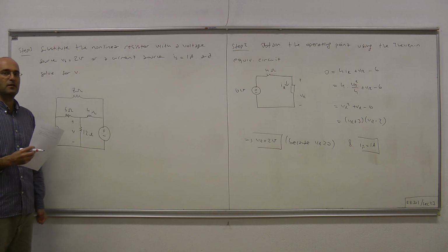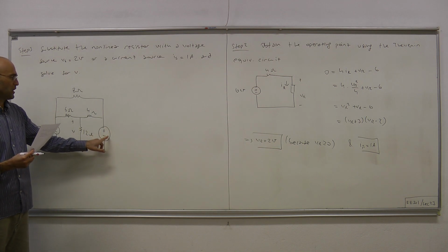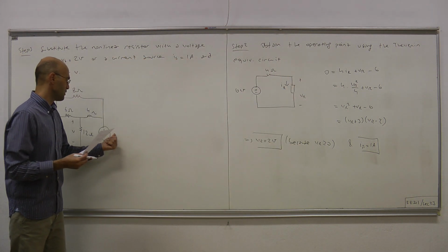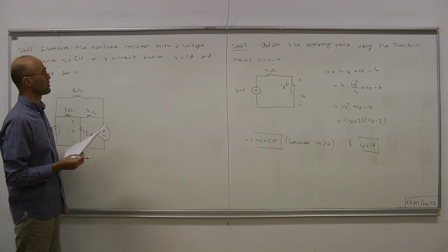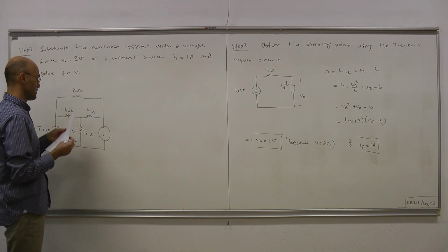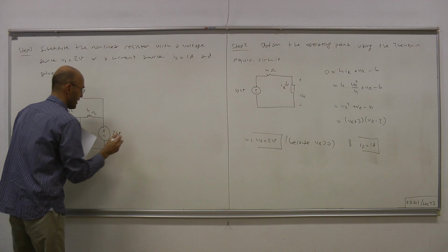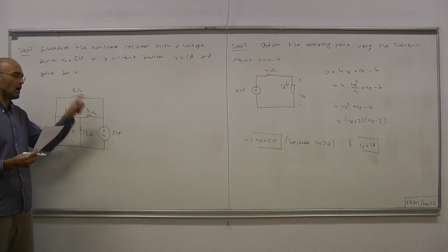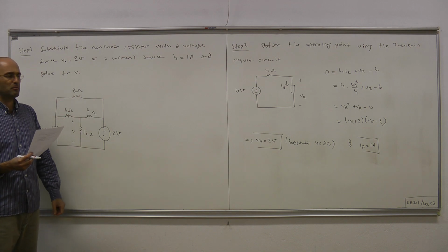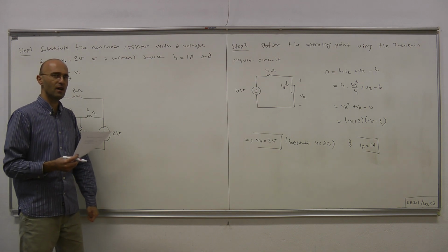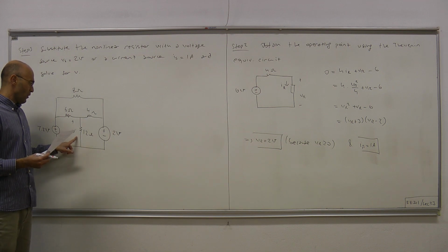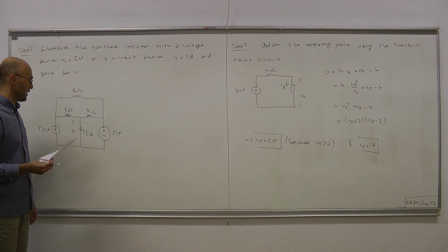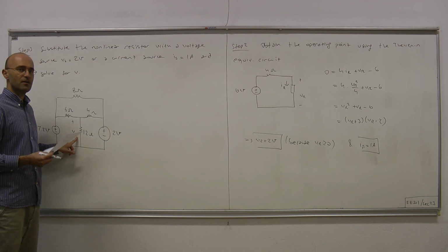Okay, let's use an independent voltage source. The polarity is plus minus, the same polarity. Therefore, the voltage given by this voltage source must equal the voltage of the nonlinear resistor. Okay, therefore we have to put here 2 volts. Note that after this substitution, the circuit now becomes completely linear. We have no nonlinear component whatsoever. Therefore, to solve for this voltage, you can apply your favorite method, mesh analysis, nodal analysis, or something else, and you reach the answer.